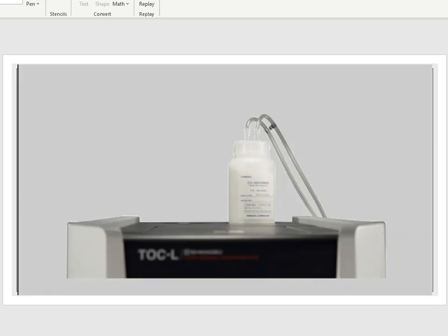So this TOC instrument normally has the CO2 absorber at the very top. And this is what you're seeing in the picture. You can see the label on the front. The label on the front says CO2 absorber, and there's two lines that basically come into the CO2 absorber. These are lines, of course, that are leading out from the NDIR detector, because everything flows through and out, and then the sample goes into the CO2 absorber.